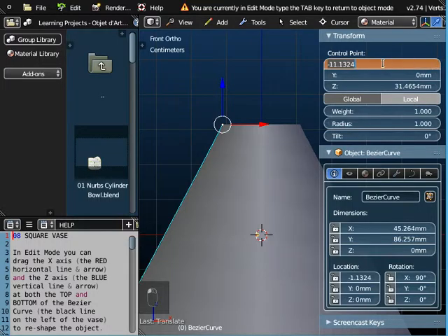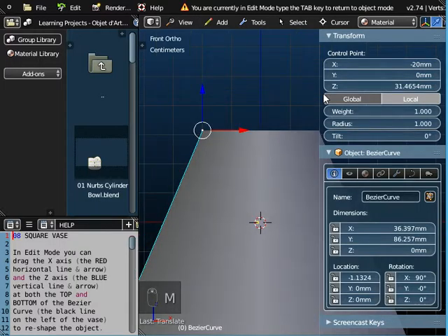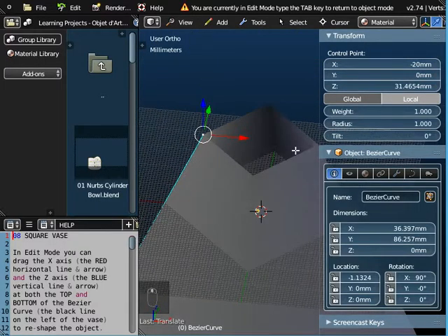So if I do that again, if I do minus 10 millimeters, I always keep forgetting to change from global to local. If we do local, so you must select local here, and we do minus 10, we go to exactly that point there. If we go to minus 20, that's exactly that point. So that gives us a gap at the top, or rather this diagonal dimension, excuse me, of 40 millimeters, because it's 20 to the center and then another 20.